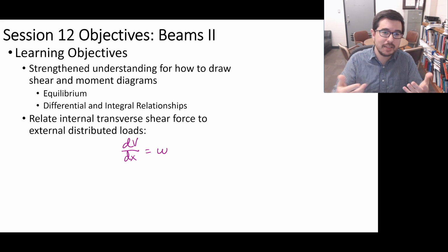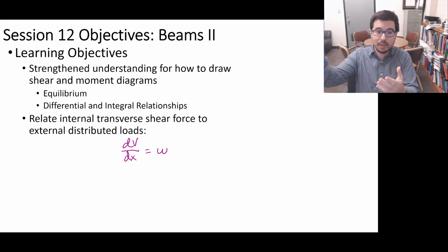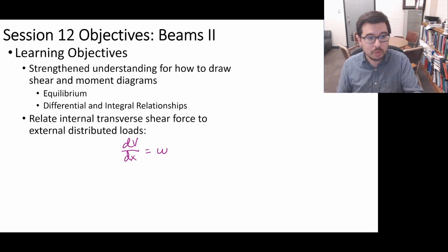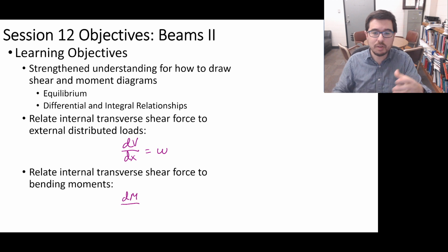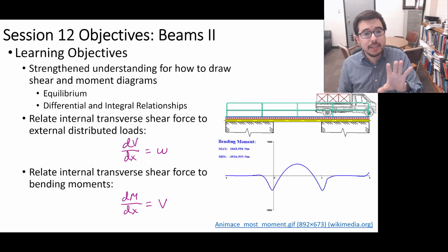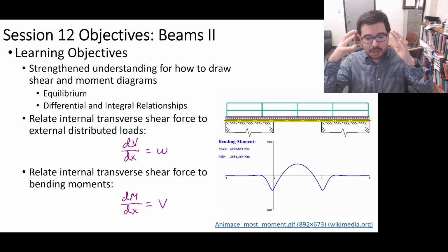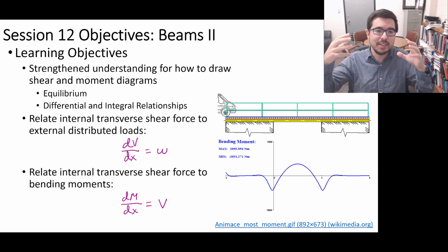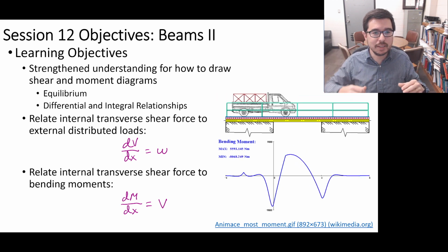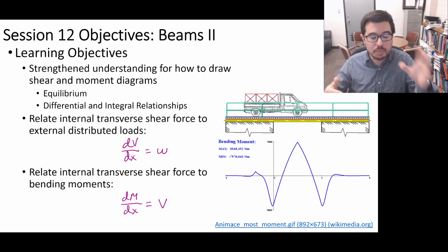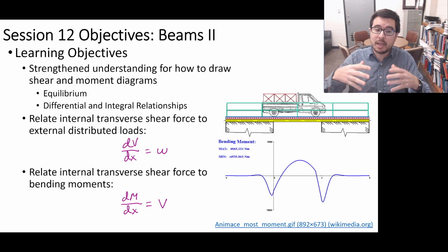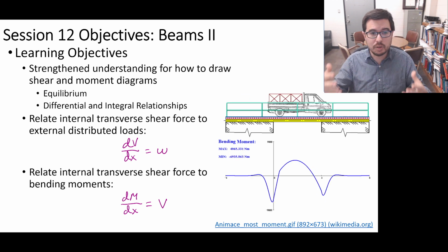And we were looking at equilibrium in part 1, and then looking at the differential and integral relationships, which include dV dx equals w, and also include dM dx equals V. And the goal here is to have this ability to start to see what's happening inside structures with respect to the internal shear forces and the bending moments. And in particular, not just any structures, but what's happening in a transversely loaded beam.